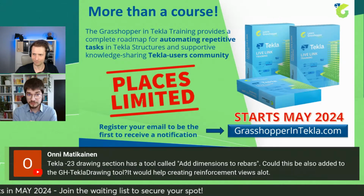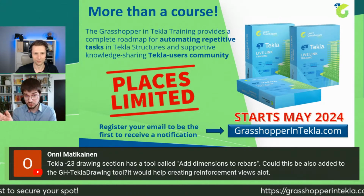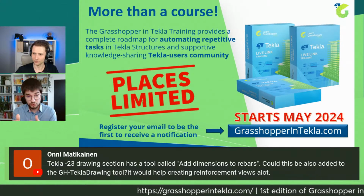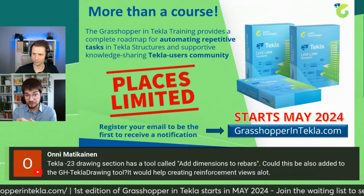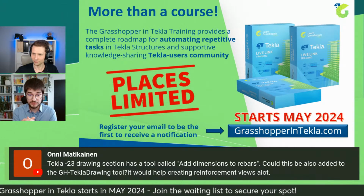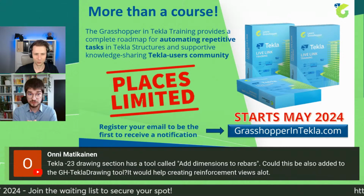So in the drawing link, there is the component Run Macro, and it can operate on the model or in the drawing. There are plenty of things which are not covered in the drawing API itself, and there is a constant answer at the Tekla forum: just use macro. Unfortunately, it has to be done in such a way when the Open API lacks those kinds of objects.